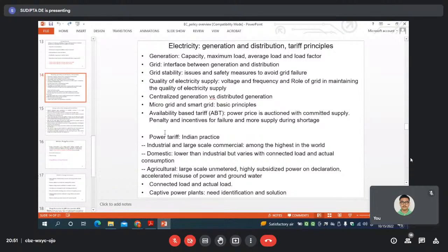Say you have a big house with 4-5 ACs. What will happen when you switch on all those ACs simultaneously? Then as a single consumer, you will consume a much larger amount of electricity, because an AC needs a separate line, a 15 ampere connection and all these things. It consumes a lot of electricity. So obviously for a new installation of any AC, I don't know whether all of you know, you have to declare to the electric company